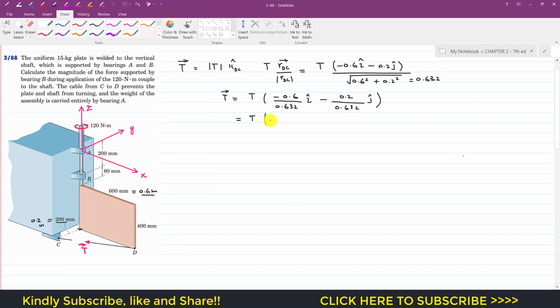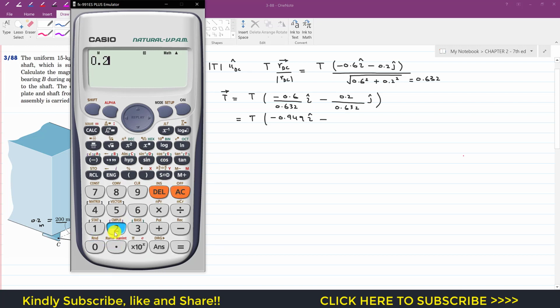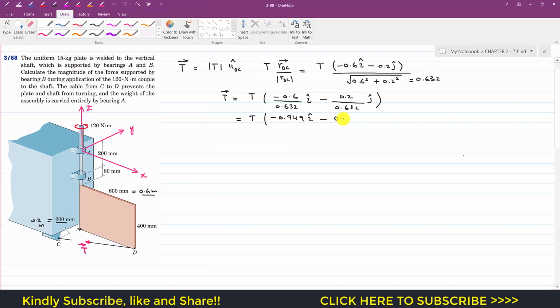So this is minus 0.949 i, minus 0.2 divided by 0.632, which gives us 0.316 j. So this is the Cartesian vector representation of the tension in the DC cable, which prevents the plate from rotation about the z-axis. This will be in newtons.